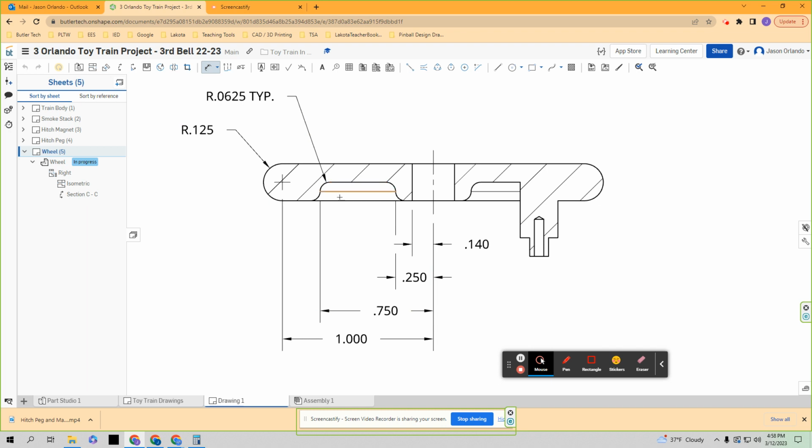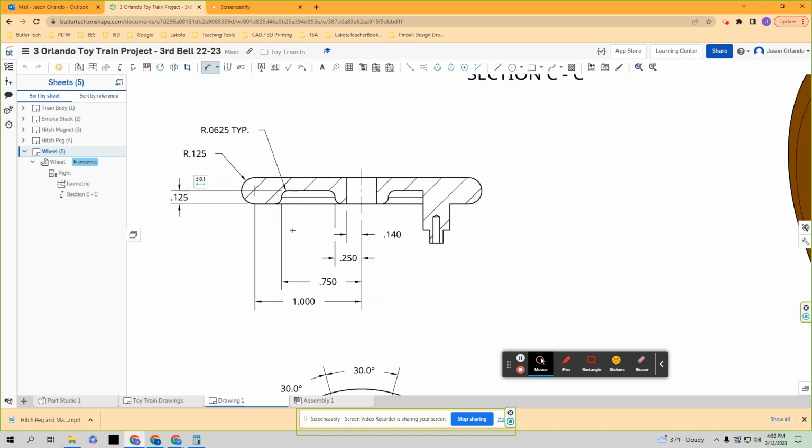I need the dimension, the depth here of that recessed area. But just for managing my extension line gap, I'm going to come all the way from here to there to bring this to the outside. That 0.125 kind of fits. Again, you could choose to pull it out.